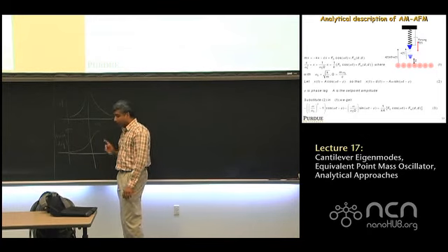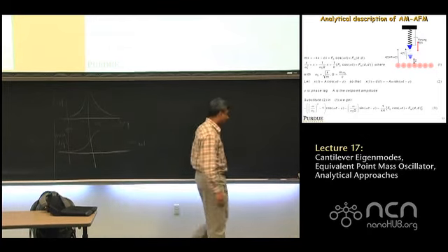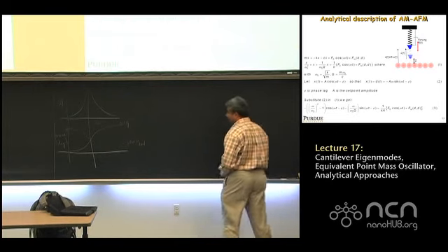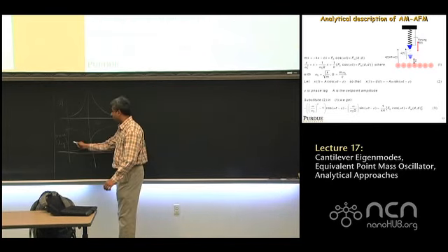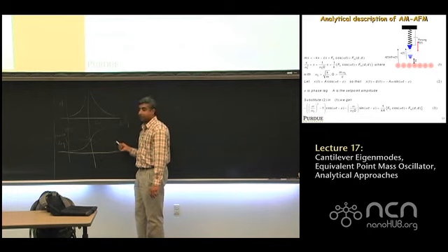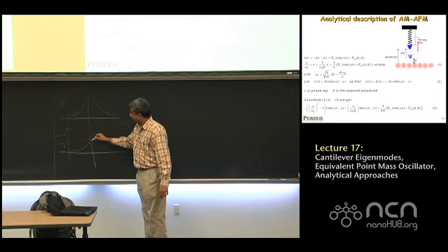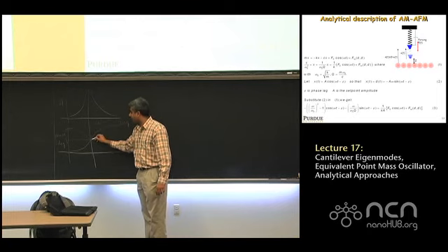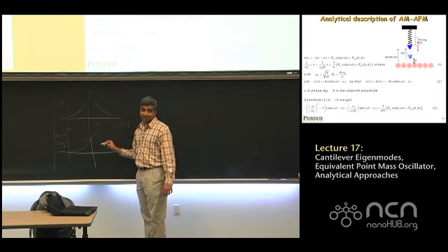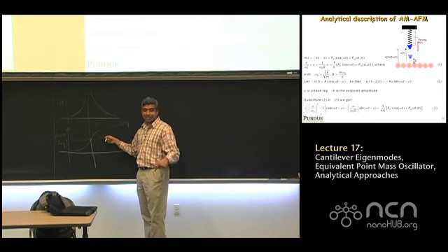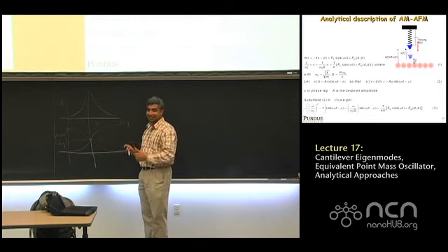Another important thing, as Ron just pointed out, is often you have to center the phase. Whatever it is, often you have to center the phase. And at the peak, you have to sort of click on this curve and make this point equal to 90 degrees. Or minus 90 degrees if it's phase lag, you would call this point 90 degrees. If it's phase lead, you would call this minus 90 degrees.